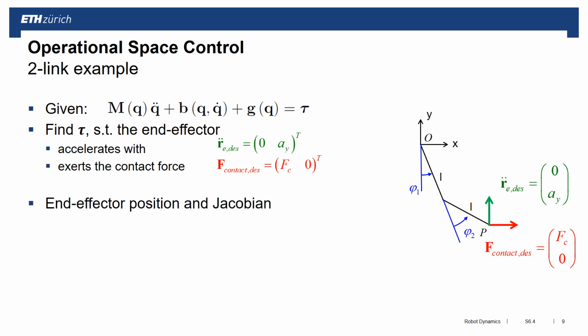What we have to do for figuring this out is that step 1, we have to transform everything now to task space, and for this we of course need to have the Jacobian at that point. So we need to have the position vector to this point, and then from this position vector we can directly calculate the position Jacobian through partial differentiation.